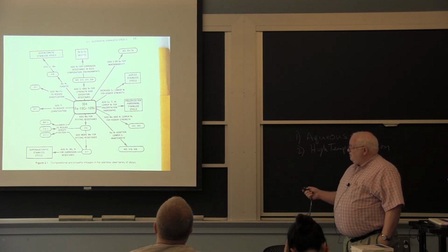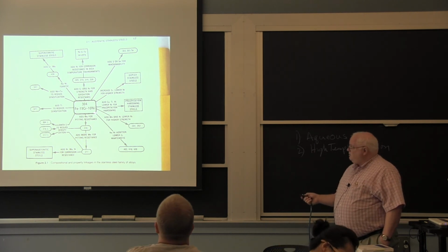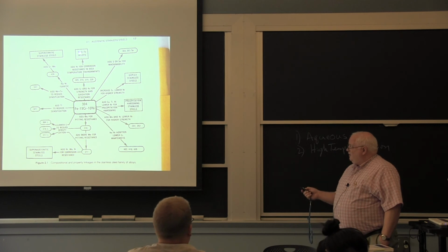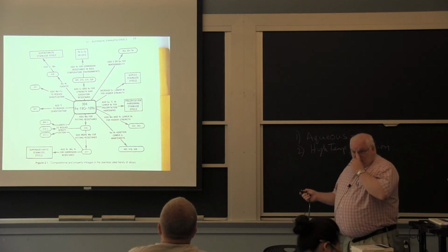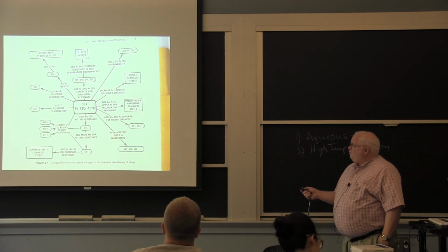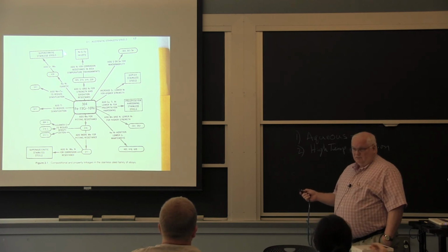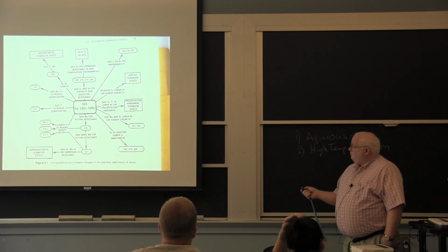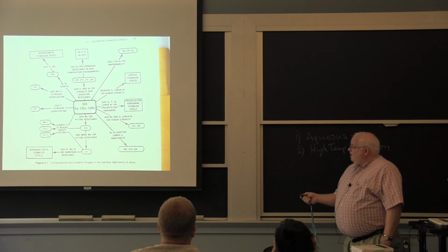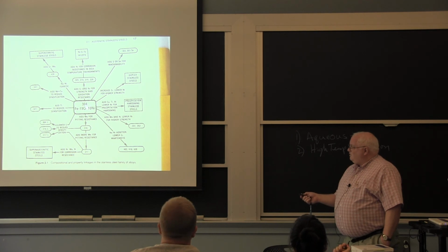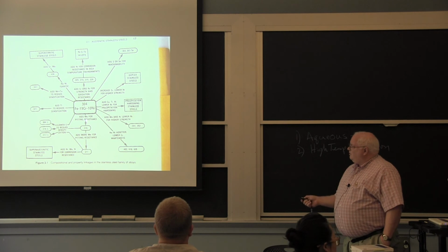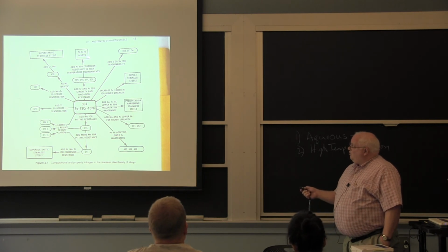We haven't gotten up here to the nickel chrome iron alloys, where you add lots of nickel, and essentially you're 60% nickel, and these are $50,000 to $100,000 a ton. But that's sort of what you build nuclear reactors out of, these types of things. Although we build nuclear reactors out of 304 for all kinds of things, because it's much cheaper, you don't want to build a nuclear reactor out of something that costs this much. Pressurized water reactors, they do make them out of this type of stuff.